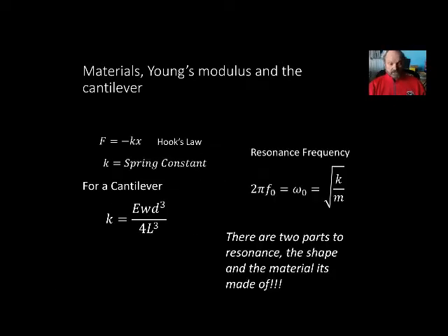And these are the equations that you saw in the previous one, but there's another equation, the resonant frequency. So if we displace the end of the cantilever and let it go, it's going to vibrate for a little while until it damps out and stops. And it has a natural resonant frequency. So you hit it and it's going to vibrate at a certain frequency. You hit it, it's going to vibrate at the certain frequency again. So it's kind of like a musical instrument. If you've looked at jaw harps, they're cantilevers, and you can amplify the sound by changing the shape of your mouth and all of that.